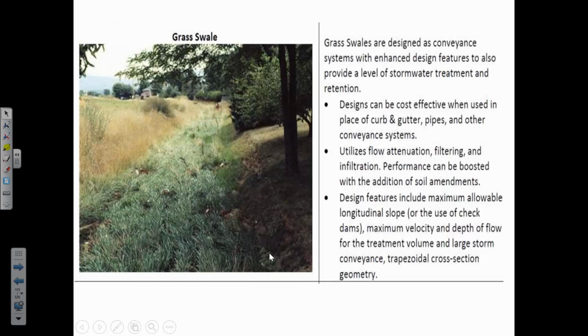All right. Ditches or a swale, if they are lined with vegetation, what that does is it increases the roughness and it slows down the movement of water. Now, it also reduces the capacity of the channel to convey, because the velocity is going to be lower and the depths will increase.